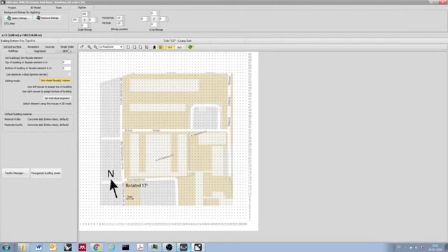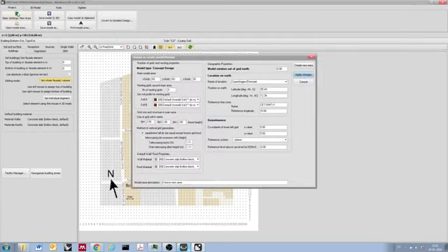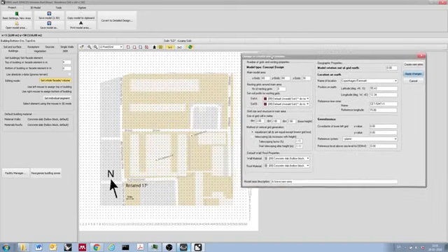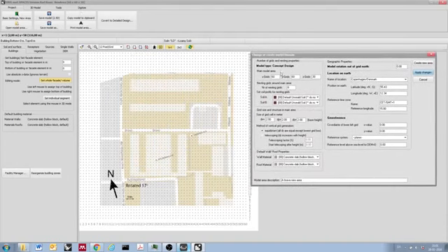To do so, we'll go back to the project and basic settings. In this space, grid size instruction main area, we will now tell ENVI that each of these grid sizes are 5 meters in all directions, assuming that our model is the same size in every direction.